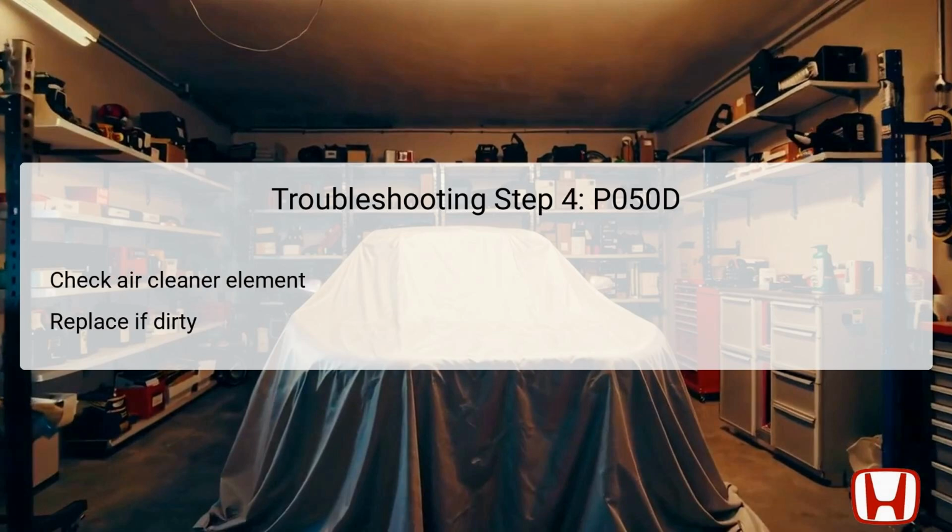In this fourth troubleshooting step, we focus on the air cleaner element. The air cleaner element filters dust and debris from the incoming air, impacting the quality of the air that reaches the engine for combustion. Inspect the air cleaner element for dirt or debris accumulation. If it's found to be dirty, it is imperative to replace it immediately, as a clean air filter is vital for maintaining optimal airflow. A dirty air cleaner can result in restricted airflow and poor engine performance, which is particularly detrimental when the engine is cold.